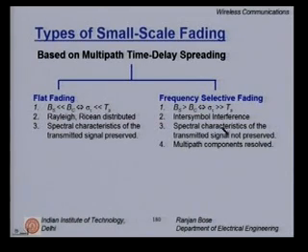But it can also be viewed from the other side of the coin, which is you can have uncorrelated fading for one part of the signal with respect to the other part of the bandwidth. So, in a frequency selective scenario, I can have inherent ways and means to overcome or reduce the effects of fading.